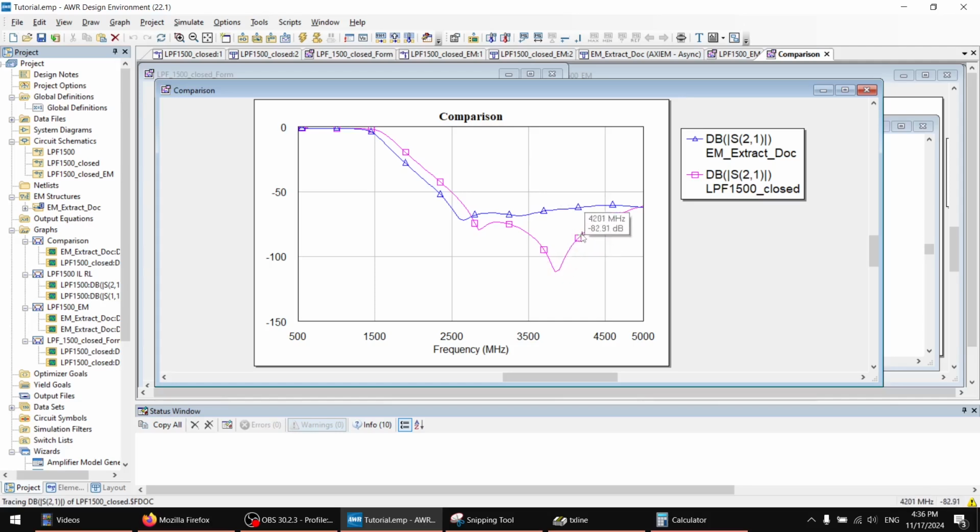So here the insertion loss is actually great, really nice, below minus 100 dB. If you have a spectrum analyzer that has this dynamic range, that would be really great. Some of course do, but maybe not all the home equipment. But this is minus 60 dB. This is very typical of a filter, even in MMIC case, of a tight case, and so on. This is quite standard result that I can completely believe in.